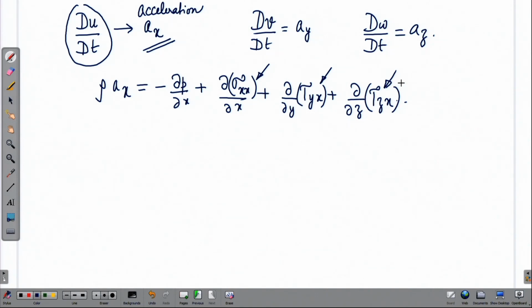That is why we are leaving it in this form, which is more compact. Now, what have we got in this equation? We have got something similar to force is equal to d dt of m v from Newton's second law. So, we are talking about an acceleration of the fluid element, which is produced by virtue of forces which are acting on it.